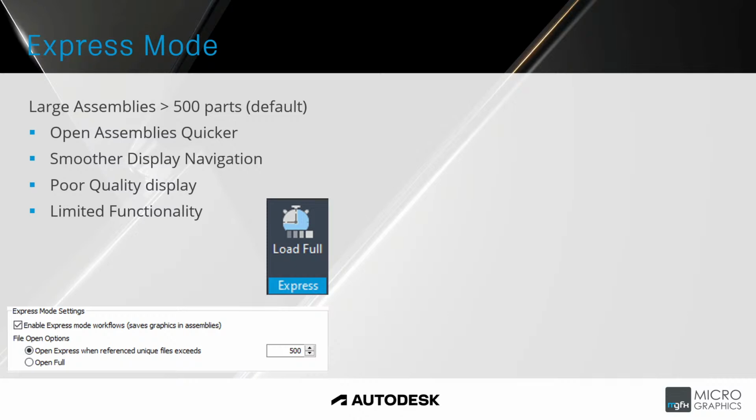So Autodesk's baseline for a large assembly is essentially 500 parts. So what happens here is when you open up your assembly, Inventor checks, okay, it's greater than 500, will load into Express mode, and it opens the assembly quicker. But it does open with a reduced graphics integrity, but also reduced functionality.